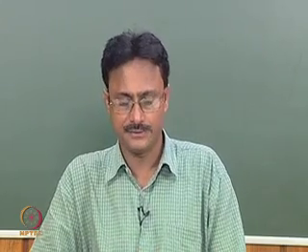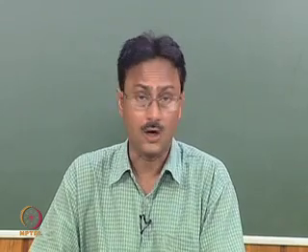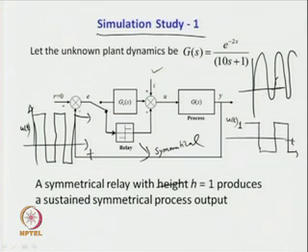Now, all the techniques and the analysis we have made earlier will fail because we cannot get a correct measurement of the peak amplitude. Now, we have got two peaks, one positive peak and one negative peak of different magnitudes. Similarly, the period we can measure, but when we resort to half period, there will be a lot of difficulties. So, again measurement of period will be there, but we will not get the correct period what is required for the symmetrical relay.